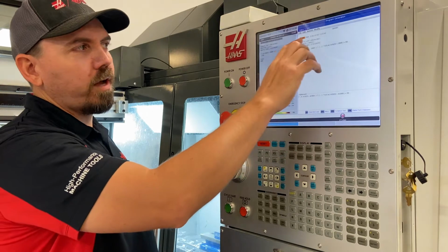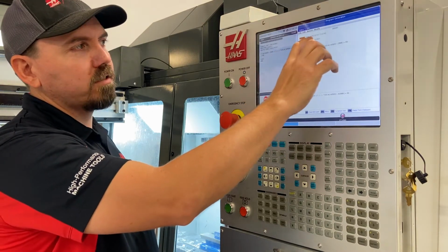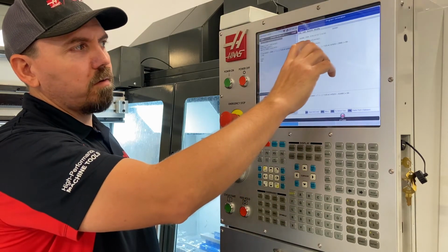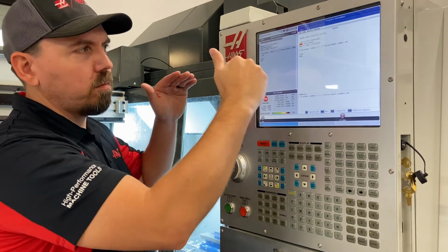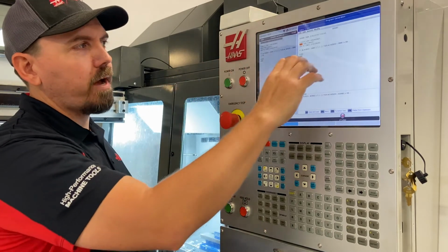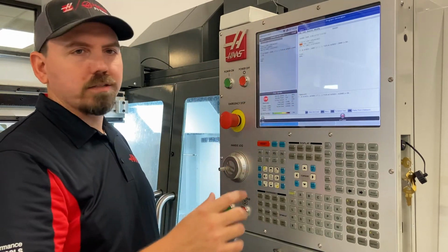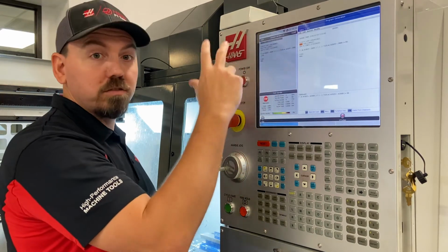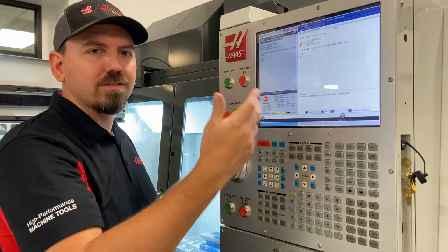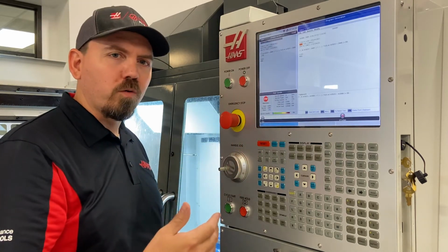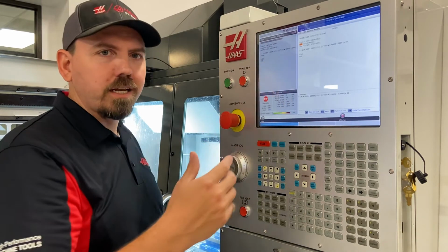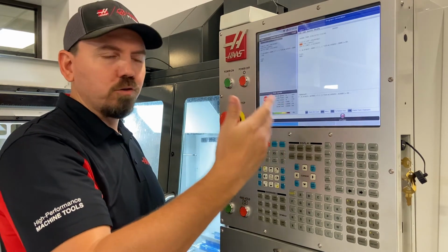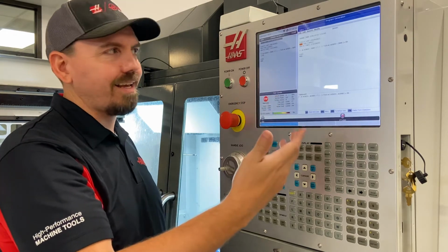In my O9001 program, I've named it M6 zero offset check. What this does is we've got limit look ahead, so we run single block one at a time. We don't get ahead of ourselves in the macros. M16 works identical to the M6. If I were to add an M6 into my subprogram for this alias code, it will never stop. It's like defining a word with the same word. So M16 allows us to command the same function, the tool change, with a different name, M16.